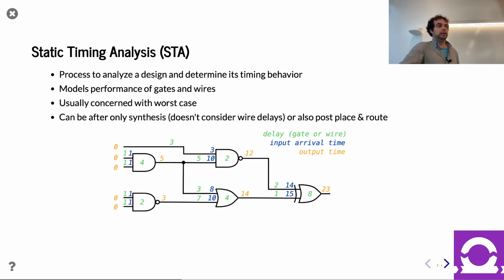Yes. Oh, great point. Here I'm talking about critical path in terms of the longest path. Isn't there a situation where sequential circuits can fail if something changes too fast? Absolutely. You must forgive me for not knowing a name for that, but yes, these are usually referred to as a hold violation. If you have a hold time violation, that is definitely a problem, and that is definitely something you want your STA tool to warn you about.